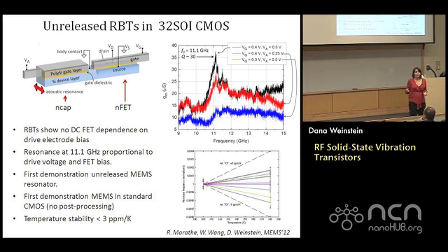We have a silicon resonator. It's surrounded by oxide. So even without trying to engineer for this, we were just trying to engineer for particular frequency and good quality factor, we were able to measure a temperature coefficient of frequency under 3 ppm per Kelvin. And some resonant modes actually showed sub-ppm per Kelvin temperature coefficient of frequency, which is fantastic for making stable frequency sources.